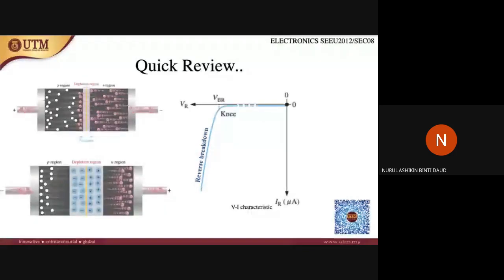All right. So the second part at the bottom, the down part here, is reverse bias, right? Because it is connected with opposite polarity with the voltage source. So the graph here is the VI characteristic for reverse bias. When you apply too much voltage, reverse breakdown will happen. So reverse breakdown will cause avalanche